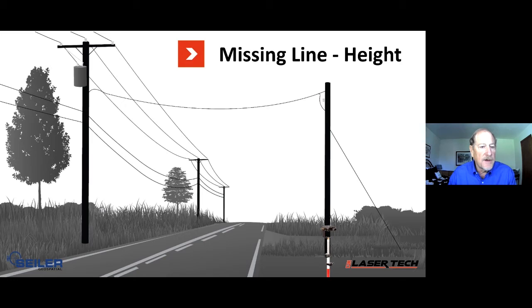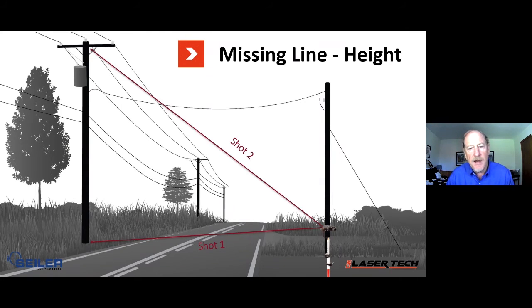In this scenario, you have to get distance and angle to both the base and the top, both of the shots you're taking. So if the base of the pole happens to be obscured, you could always put a marker 4 feet up on the pole, or on some other object there, shoot that and just add it in. You take shot 1 to the base, distance and angle, and then you take shot 2 to the top, again distance and angle. Then it will give you a solution of all the information in between, and you just scroll around to the vertical distance value, which will be in that vertical space, and that would be your height essentially for that type of leaning object. So that's another way you can get that value.